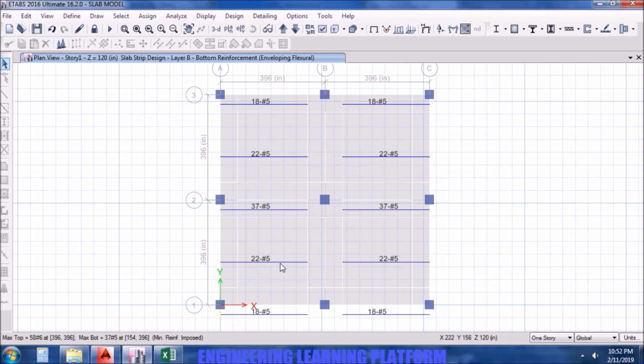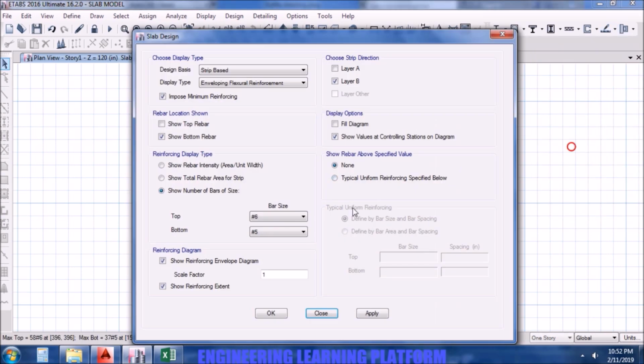Since the rib width is 6 inches, 2 bars can be placed in each waffle. The maximum allowable bars are 24 in each span because there are 11 waffles, which we already calculated.